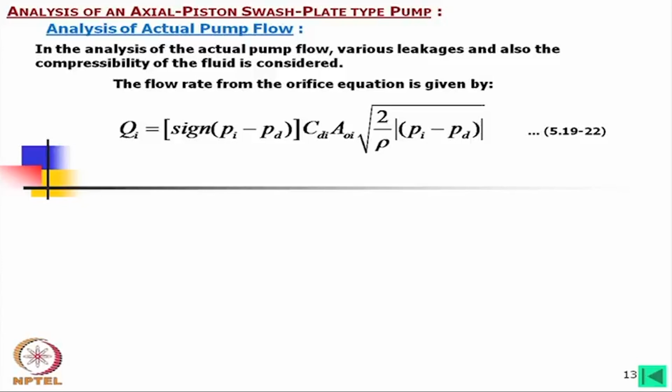the discharge, that also we should verify depending on the shape and size of the orifice. Usually there is no way but to go for the experiment, but what is done normally is, depending on the orifice geometries, irrespective of their physical sizes, depending on the shape, at different openings of such orifices, the CD will be fixed.